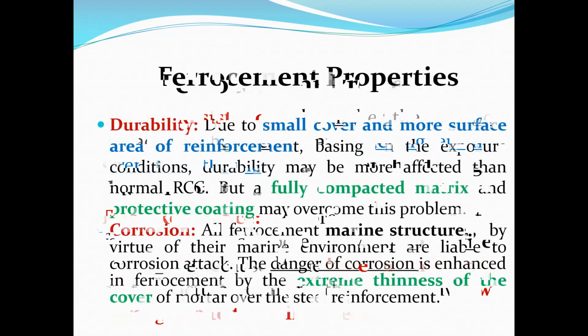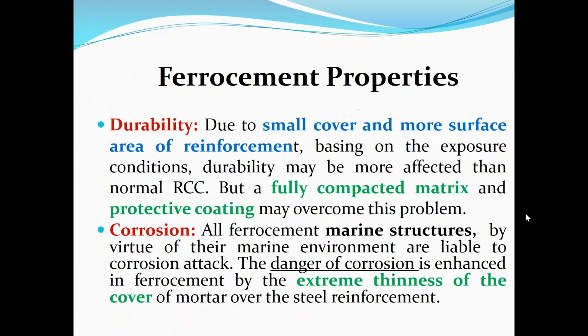And then durability. The concrete cover is small, so based on exposure conditions, durability is affected more than normal RCC.